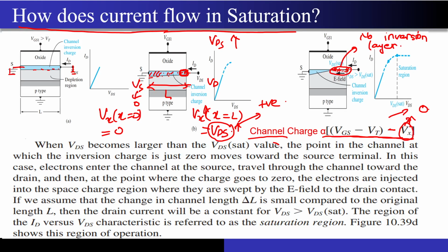This is one question that they generally ask in job interviews or in PhD or MTech interviews. So what is actually happening here? I have a depletion region. Even though I don't have any inversion layer present, my field is so strong here. Let me give you a small hint: L is, let's say, 1 micrometer. Then this gap that you are seeing, let me highlight it as delta L, it will be even less than 15% of your L value. So this delta L is very small, and I have a certain potential here.